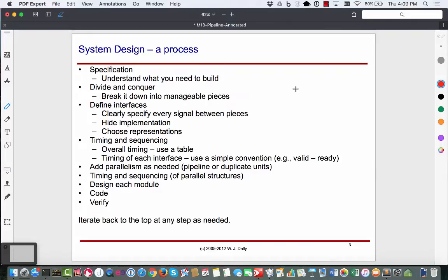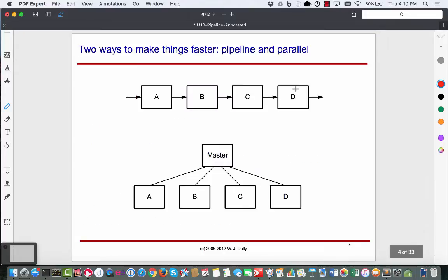You play with the architecture, and there are many systematic ways of doing it. Some of these things EDA tools apply for you automatically. Some of them you may have to direct the design towards. And then, of course, you build the stuff. As I mentioned a few moments ago, philosophically, ignoring the better algorithm and better gates part, there are two things you can do to make things faster: do things in parallel and do things in a pipelined fashion.